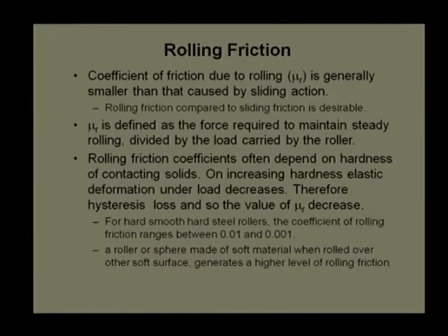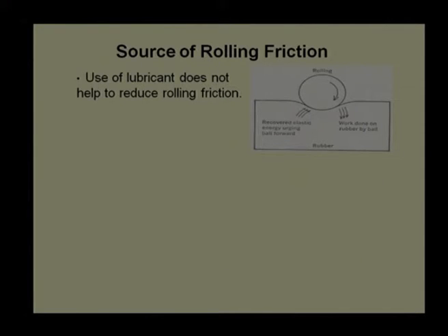So, 4 mechanisms, but we are assuming, for timing, that we are not going into the plastic domain. The plastic domain coefficient of friction is neglected in this case, and there is a very low chance of micro slip and very low chance of excessive heating. So, we will consider only the elastic case. Suppose elastic deformation itself is going to give a coefficient of friction.